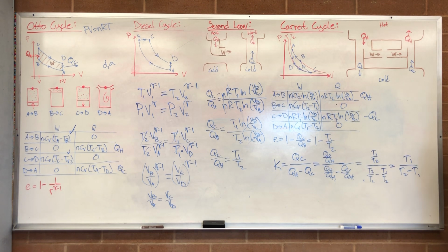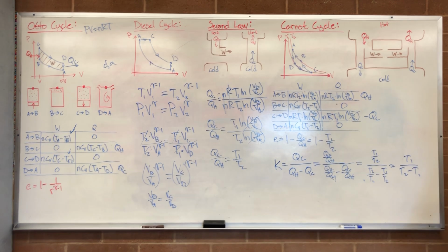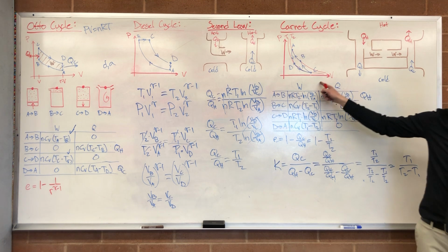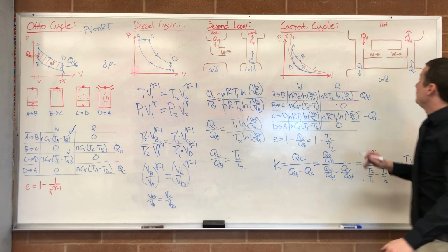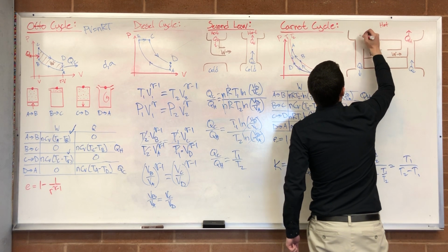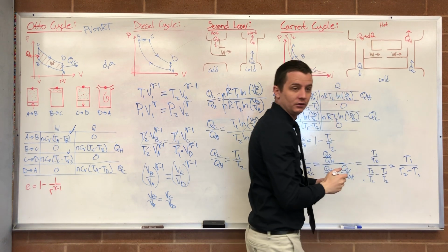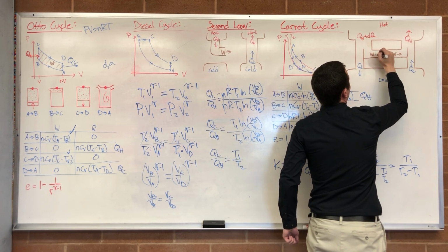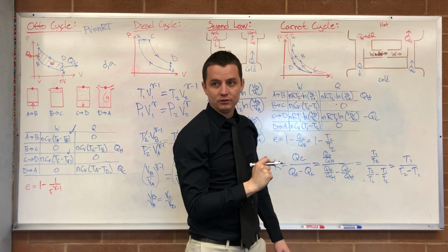Right? Now let's assume that for some reason, somehow, with some crazy technique, using some sort of crazy quantum mechanics and whatever, you were able to make an engine slightly more efficient than the Carnot engine. You're able to come up with one that's just slightly more efficient. So that means when you add just a little bit more heat, so when you do Q sub H plus some teeny extra bit, then you're able to get just an extra bit of work out of it. So you're able to get W plus dW work out of it. You with me?